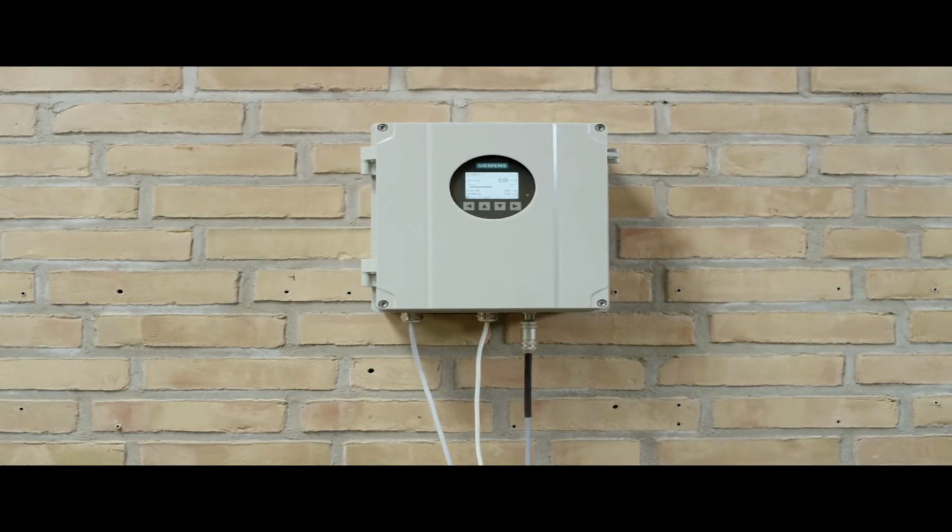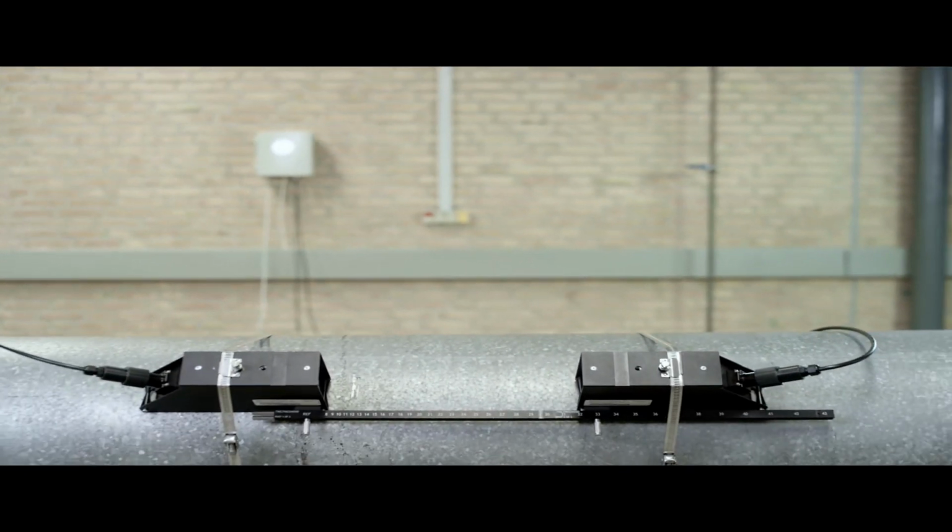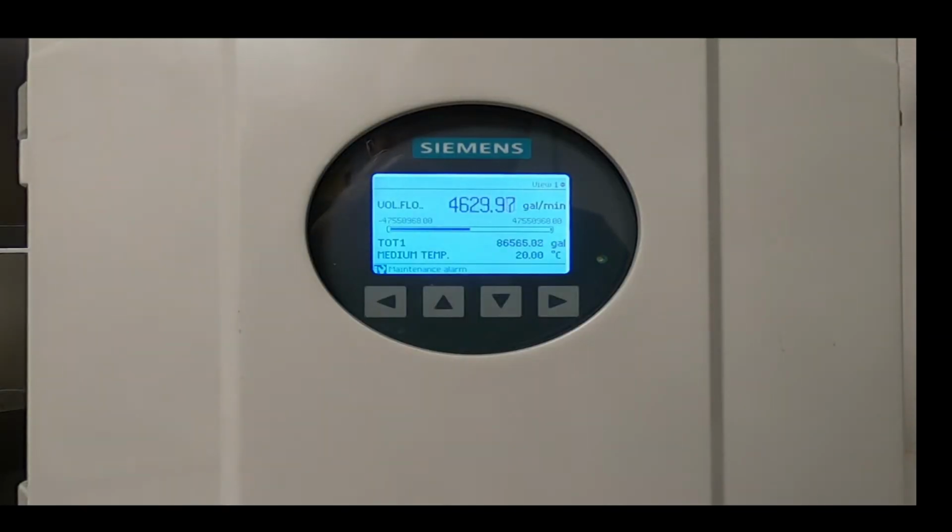You've installed your FS230 or FS220 flow meter and initiated flow through your pipe. The FS230 responds and is providing proper flow readings, but due to the high flow rates of your application, you would like to change the resolution of both your flow rate display and totalizer. In this example, the flow indication is in gallons per minute, and the totalizer is reading directly in gallons, which may cause it to quickly overflow. A better solution would be to change both indications to read 1,000 gallons or K gallons resolution.